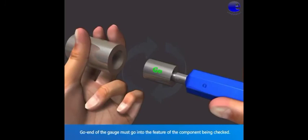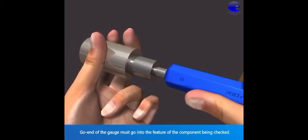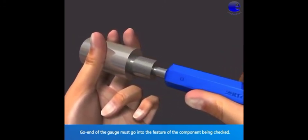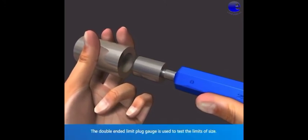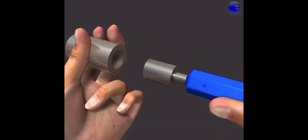The go end of the gauge must go into the feature of the component being checked. The double-ended limit plug gauge is used to test the limits of size. This type has the advantage of easy handling.